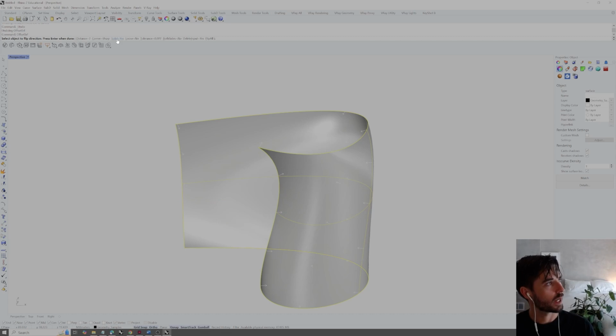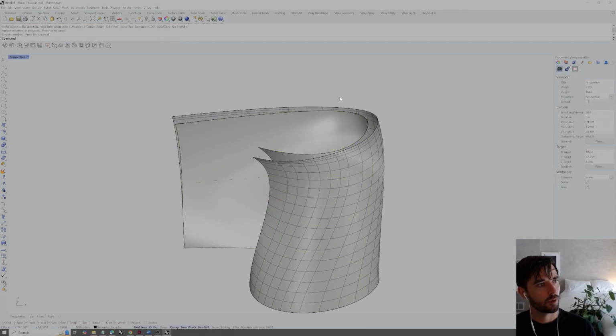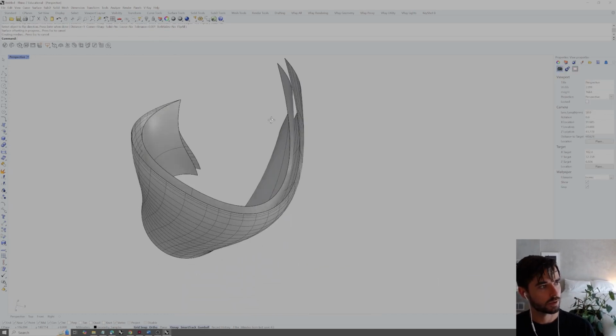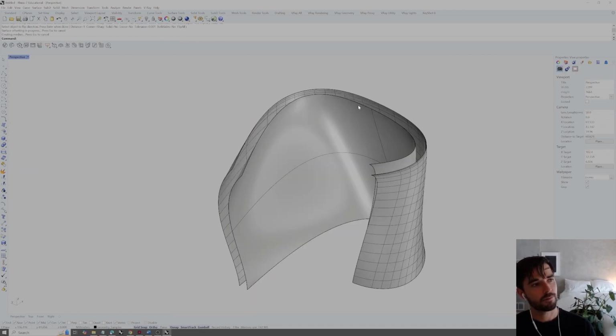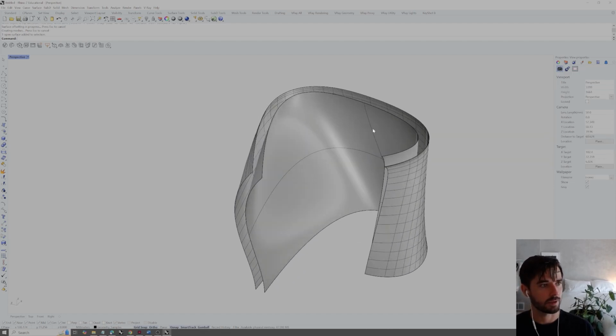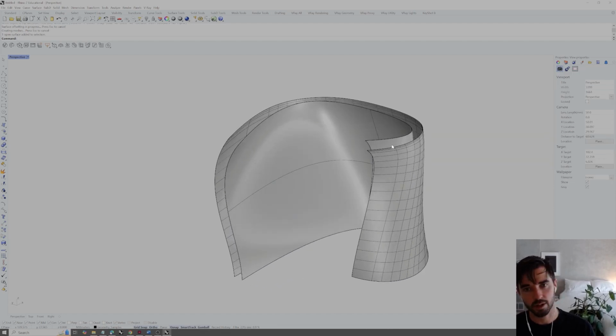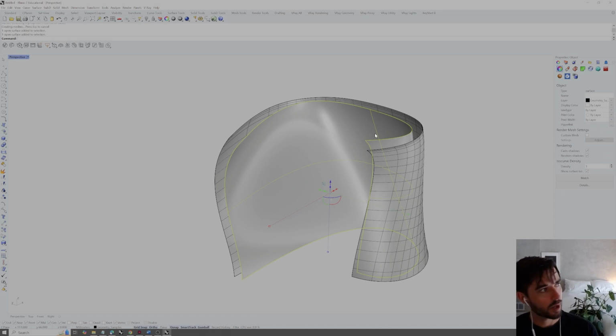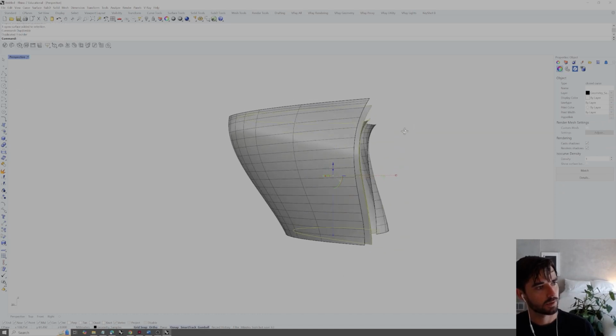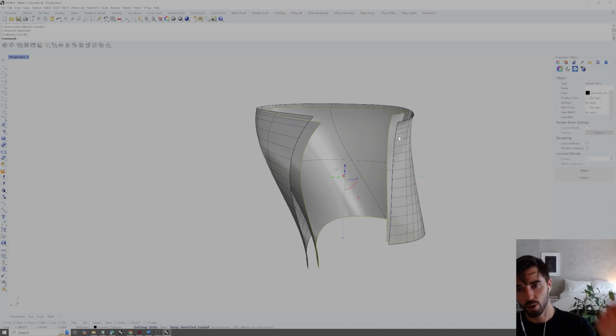If we were to do that same offset outward, but we select solid no, we now have a gap between these two surfaces. If we had this and we wanted to connect it, so let's say we happen to have these two surfaces, we want them to be solid to 3D print, one operation we can do is type dupe border, which gives us the duplicated open border of both surfaces.